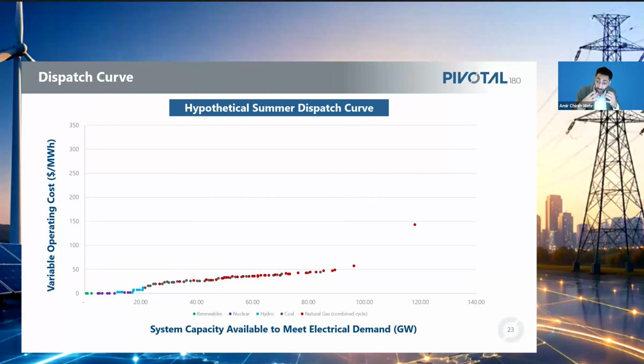But then that combustion reaction itself on a chemical level is producing really high temperature steam, which you capture in the second cycle, hence the combined cycle, and run through a steam generator to capture that energy of the water vapor, the steam that would otherwise be vented out, right? So it's more expensive than single or open cycle power plants, but the virtue, of course, is you're capturing not just the energy from the combustion, the burning of the gas in the first instance, but the water vapor, the high temperature water that results as well. In some contexts, obviously, you also build those single and open cycles. The biggest difference being, unsurprisingly, that you let that waste energy go.